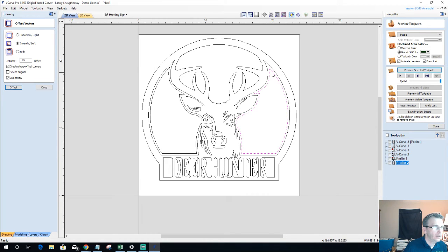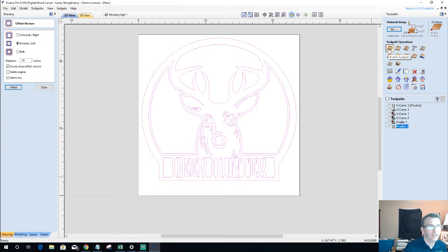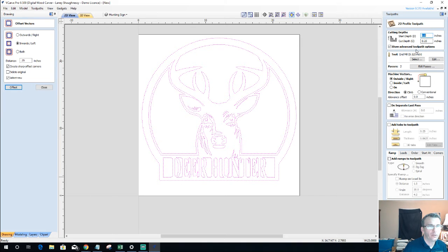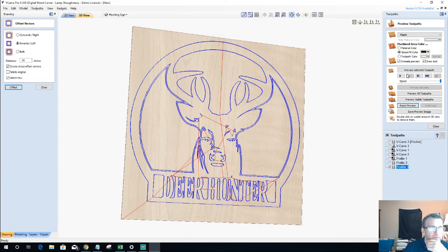Bear with me a second. There's a lesson to be learned here. There's something that could happen with this. That was profile cut. It'll be outlined there. Here's the best thing about this software. We can preview. So let's create a profile toolpath and let's see what we've done. I'm going to cut through my material with my 1/8 inch bit. I'm not going to add tabs right here. I'm going to calculate this. Reset our preview and let's look at what we've got here.